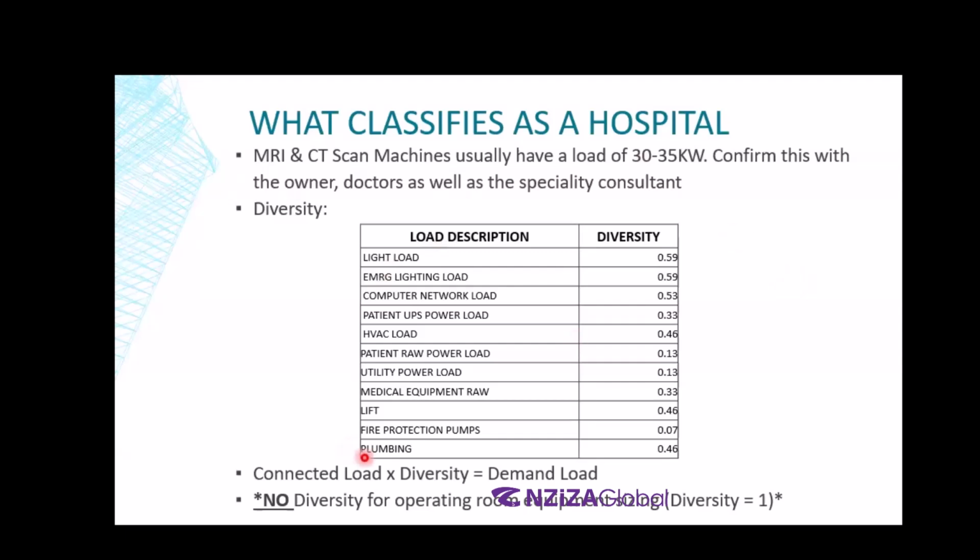Similarly, you have different types of diversity factor. Basically, the connected load into the diversity equals the demand load.